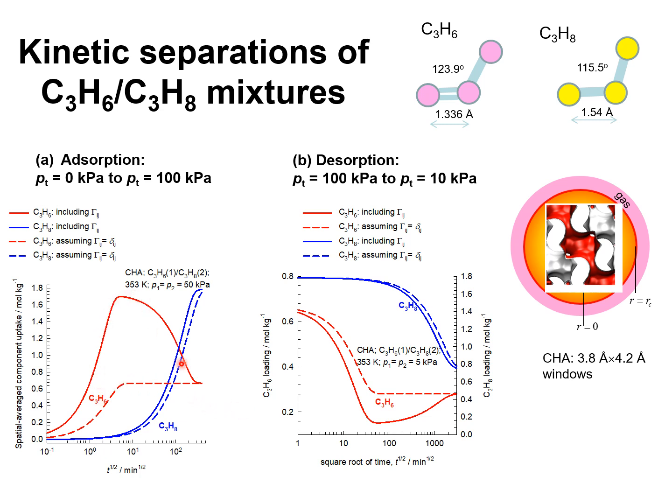Overshoots in transient uptake and undershoots in transient desorption of the more mobile propene is a direct consequence of thermodynamic coupling effects in mixture separations.